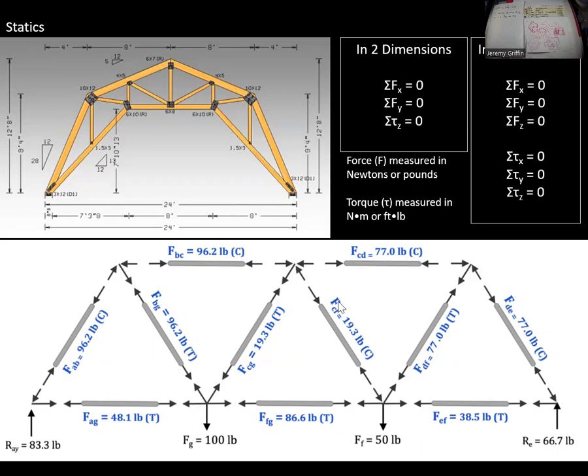So let's say you're building like a truss bridge, right? You would want to know what are the stresses on each part of this bridge. And if these conditions are true, if the forces and torques have to sum to zero, you can do these calculations. So you might pick this joint point right here. And then you might want to figure out, well, is each of these pieces in compression or tension? When you guys built those toothpick bridges, right? That was a good question. It's like, well, what parts are going into tension? What parts are going into compression? And would the tension or compression exceed the maximum possible tension or compression of each part? You know, is this bar here too skinny, or is it made out of the wrong material and it's just going to crack apart? Right?